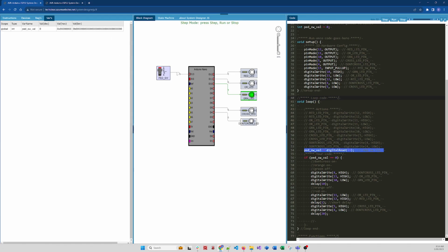The pin has gone to 0, the input circuit has been detected as a logic 0, and that is stored as 0 in memory. And if I release the switch again, it's now going to still keep that 0 stored in memory because it's already read it. It won't change that value until it gets back to here again. So let's just step through this. If the value is 0, then do something with the lights.